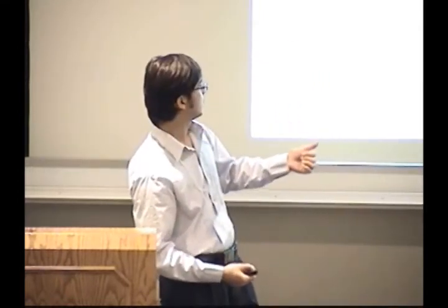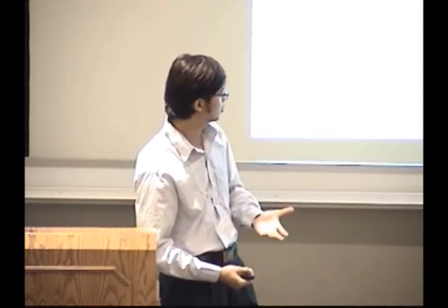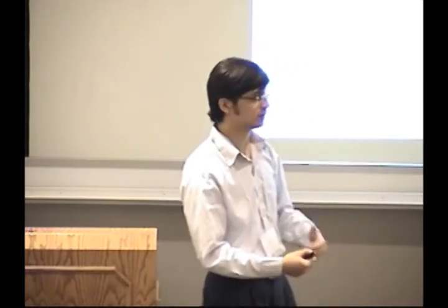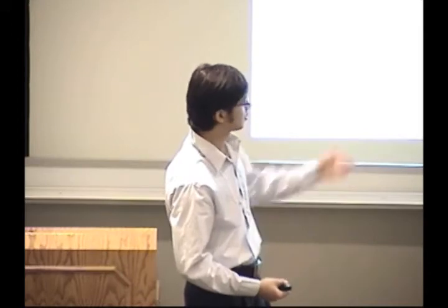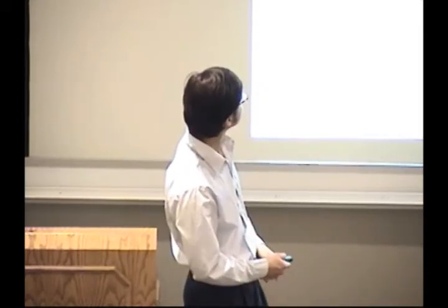Pressure sensitive paint is again a way of measuring the pressure on a surface. It's basically sensitive to the pressure, the intensity of the light that is displayed by the surface of the paint is proportional to the pressure that it sees. I'll explain helium tufting when we come to that.